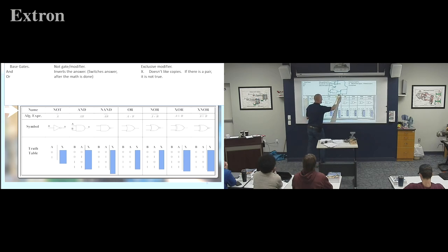Except I want it to be normally closed. I know how to draw it in the other diagram, but we haven't done them much. So this would be a NOR gate, right? This was my OR gate. If either one of them is closed, it turns on the solenoid on my contactor, and my contactor is going to reverse whatever you were doing, basically. I think that would work.